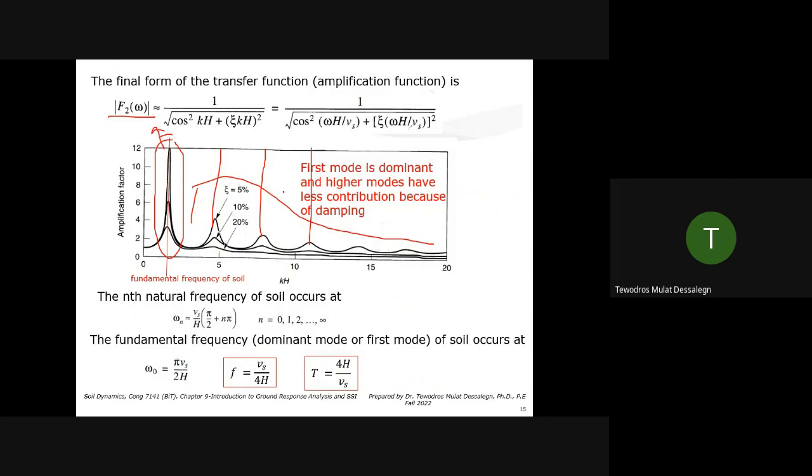The first mode is the dominant one. You pick that acceleration in the pseudo-static analysis, but for the other modes, researchers found around a 33% increase. But the recommendation is to go up to a 50% increase to account for the other modes.